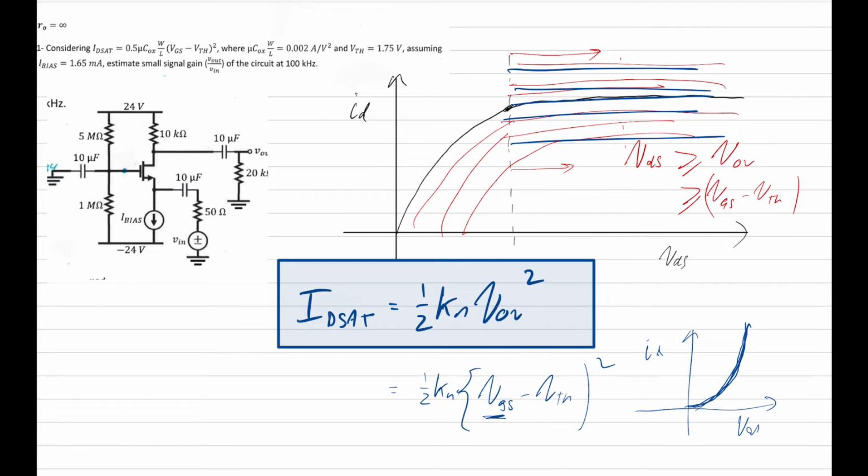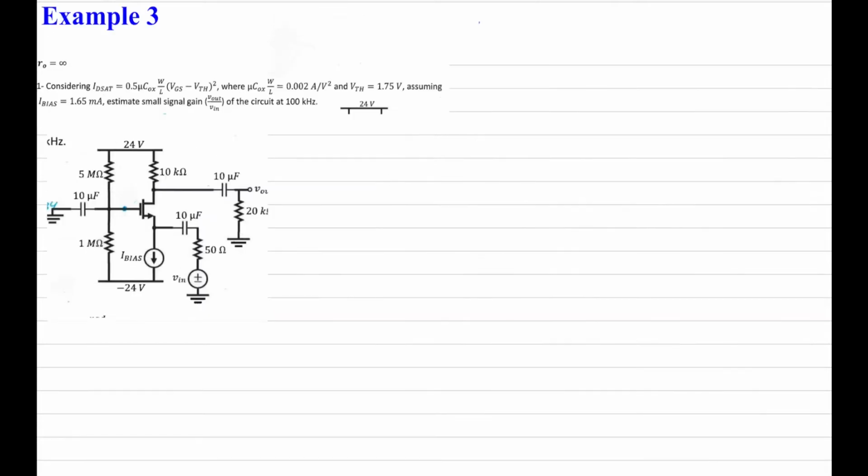So the first thing, when you're getting into a MOSFET question, is just to recognize the ID, which corresponds to this part over here, in the saturation region described by this equation. This is really like the golden equation for MOSFET analysis. Now, we're given the equation for ID sat, which we really know already. We're also given Kn, this parameter, and we're also given the threshold voltage as well. So let's proceed to answer the question here.